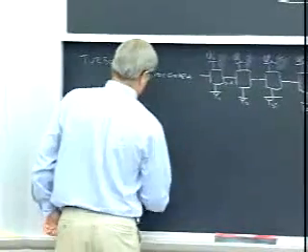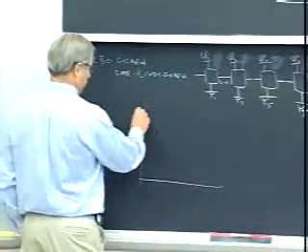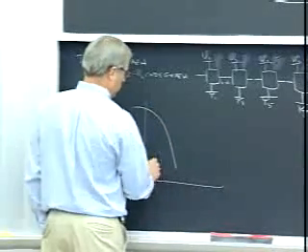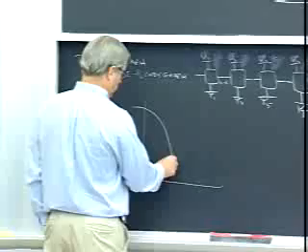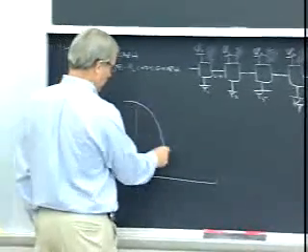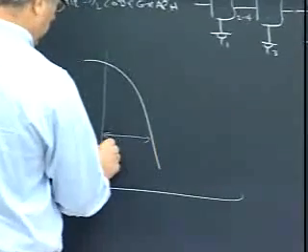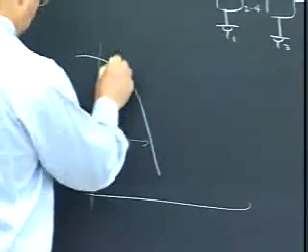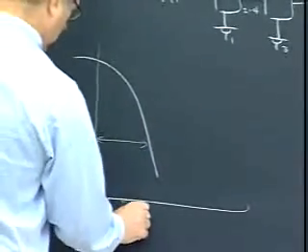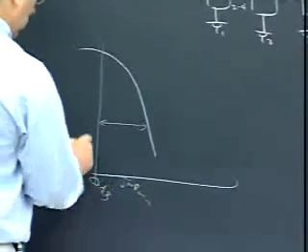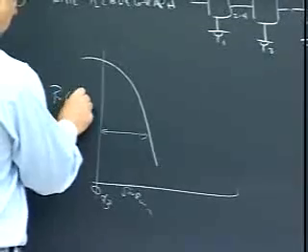In all these codes, when you draw the performance curve, as we always draw it, you tend to get what's called a waterfall region, where things behave in a very steep Gaussian-like manner. When you measure distance from capacity, let's do this versus SNR norm. So capacity is always at 0 dB, and this is probability of error.